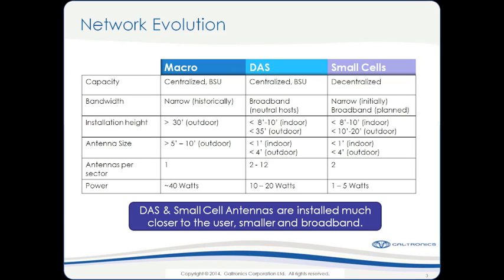So this is significant in that you may have 4, 5, 6 antennas on a single sector, and because they're on that sector, the definition between coverage from one antenna and the next isn't so significant because all of those antennas are on a single sector. You do still have to be concerned with sector boundaries where you have a group of DAS antennas that now come in close proximity to the next group of DAS antennas. This is a so-called sector boundary, so you still have those concerns there, but it's not with every antenna as it would be in the case for macro.